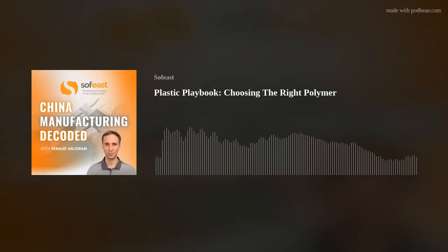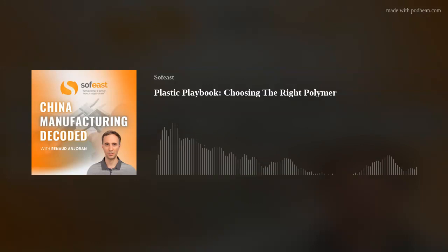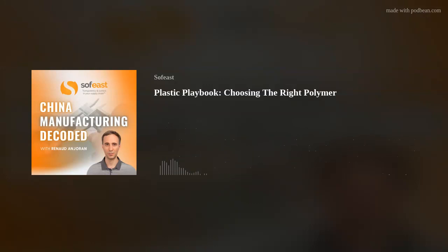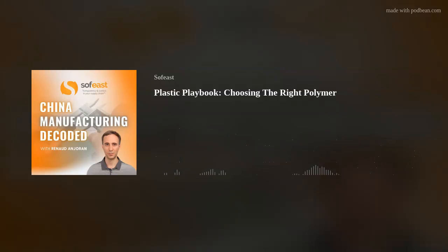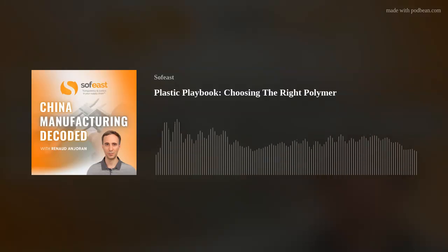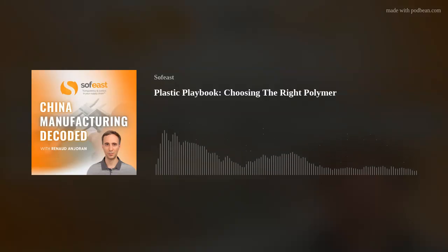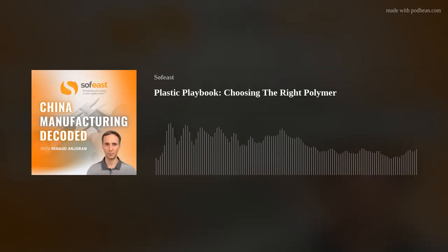Now, another very, very popular additive or modifier is UV protection. Again, this is commonly used on products or components that are being used outdoors, where they need to remain outdoors and exposed to the elements for a long period of time without discoloring, without changing the mechanical properties. In other words, going from a tough material to a brittle material that breaks, then exposes the electronics inside and exposes hazards. That's no good. So we add in UV protection modifiers to the actual raw polymer itself.